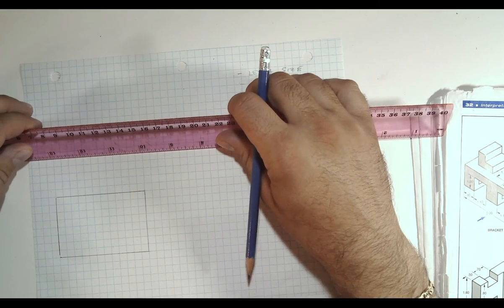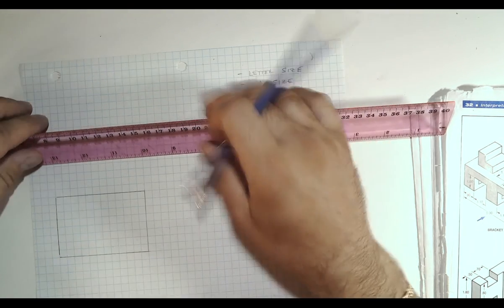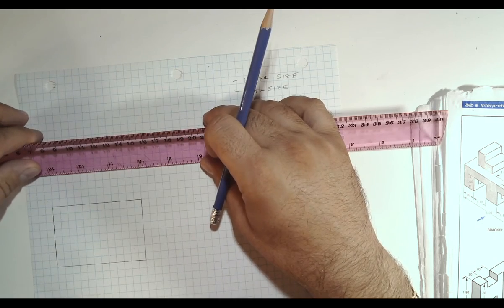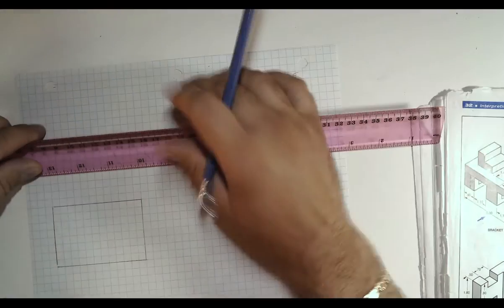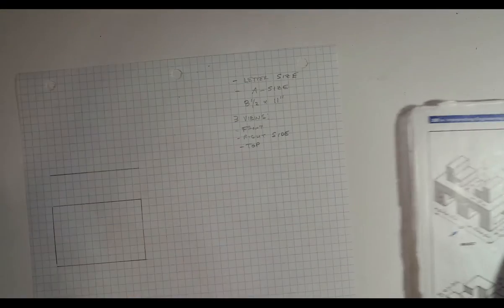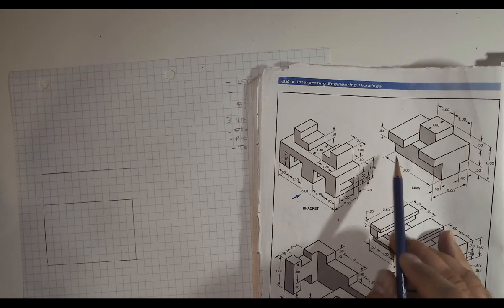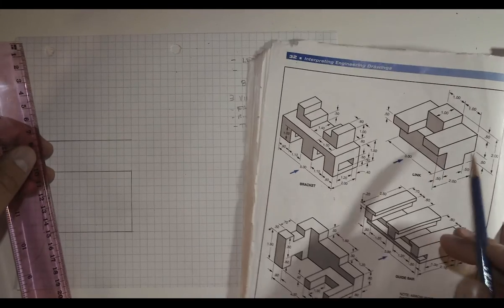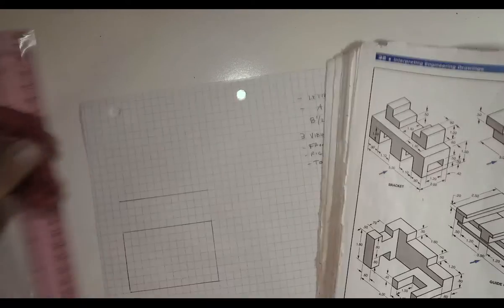So they're used in the construction of the drawings. So I'm going to space my views an inch apart. So 4 grid spaces equal 1 inch. And I know the width of my top view, the maximum width of it, the overall width, is 3 inches as well. Okay, and the depth of the top view, you can see on the diagram, is 2 inches.